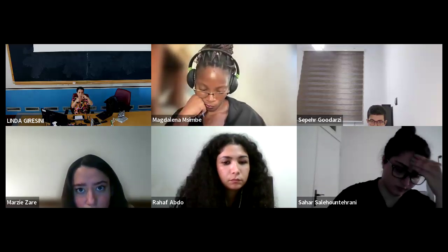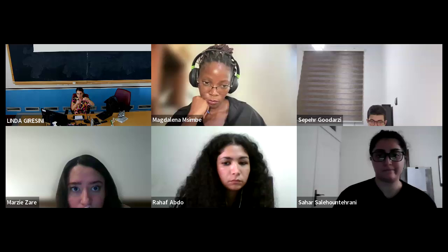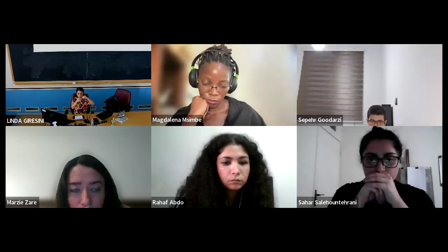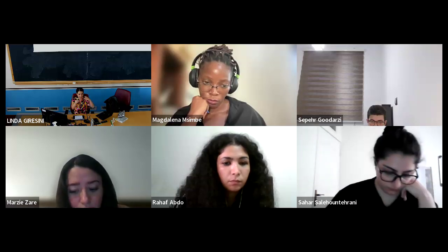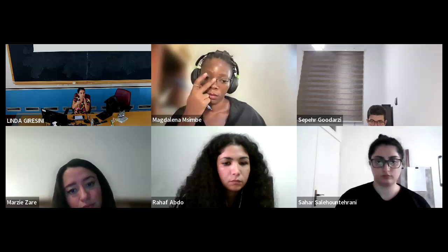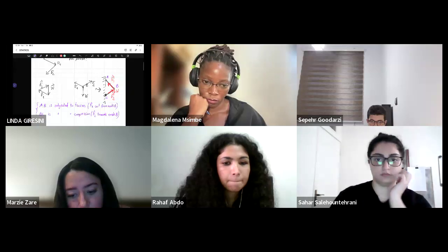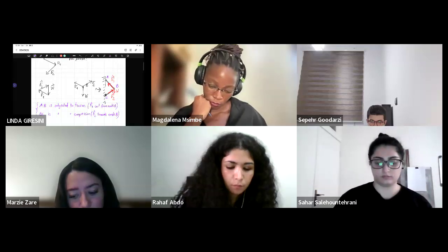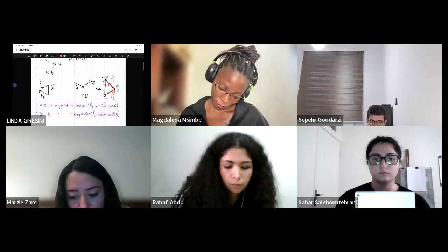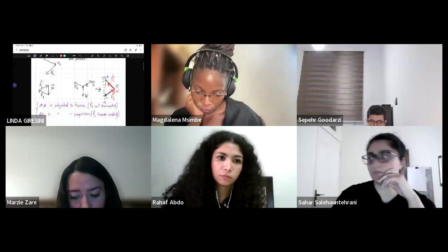When an element is lengthened, it means that it is subjected to tensile force. And when an element is compressed, then it shortens. So it was comprehensible since the beginning that the upper element, AB, was in a tensile state, and the element at the bottom was in compression state. So it's just a matter of this consideration.